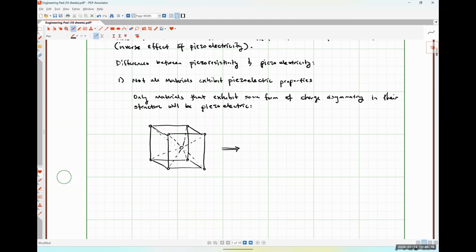If we wanted to make this piezoelectric, what we would do is a process called poling, okay? And so poling occurs, and I'll write this down in a moment, by aligning all of the dipoles of the material to an external electrical field, and then effectively heating the material up to lock that in. And so the result of poling might look something like this. Once again, I'm going to try to loosely draw something that's body-centered.